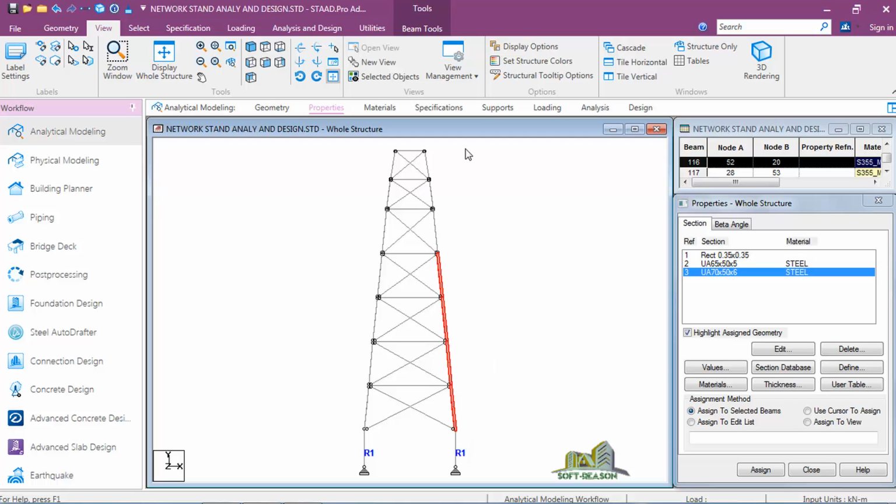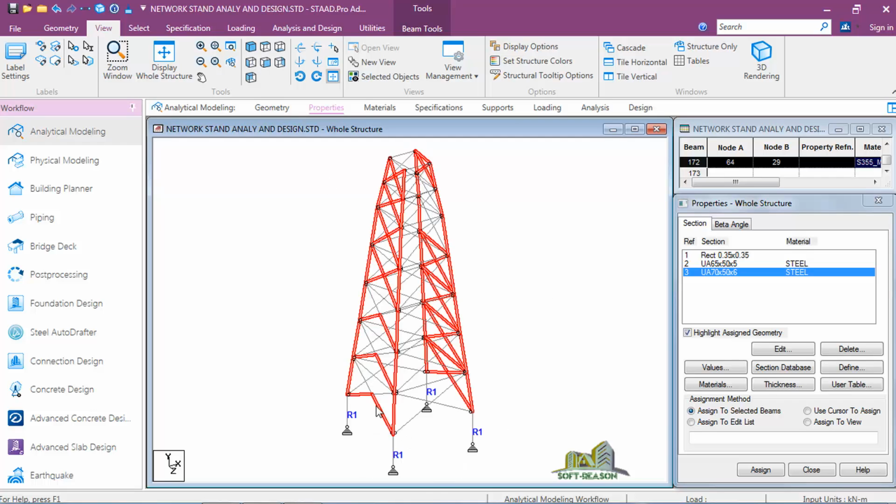Hold the control key and highlight all these, and do the same thing here. Highlight all that are in this axis. Check your orthographic view; some of these have also been highlighted, so what you need to do is remove them by holding down your control key.